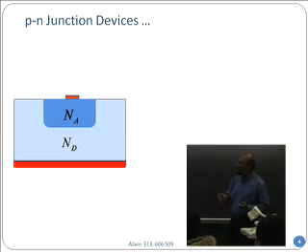As a result, there is one region where Na, the acceptor atoms, is much larger than the background Nd. Not that the Nd has disappeared, but Na has superseded the value. And you can see the dark blue and the light blue, the perimeter around it, that will be called a junction, because the majority dopants change from one type to the other.